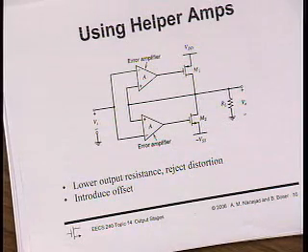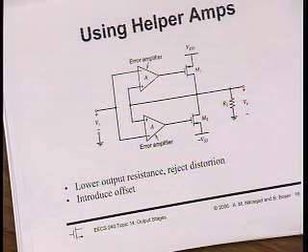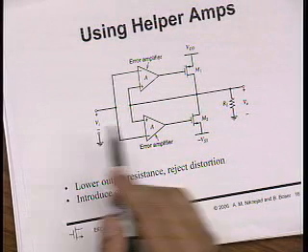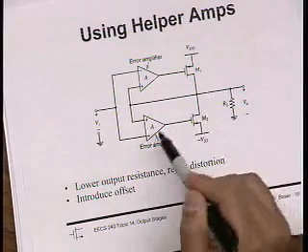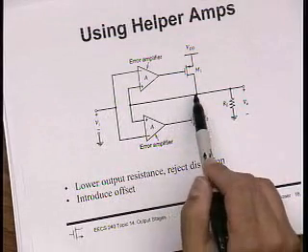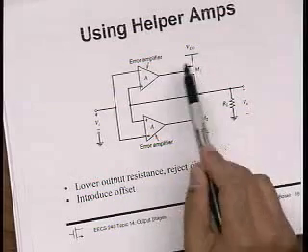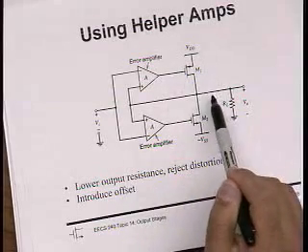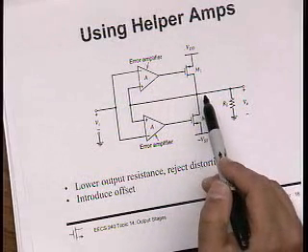So you have an amplifier of gain A, you have a transistor with output resistance RO. Yeah, RO over A, right? It lowers your output impedance by, in fact, A. As we said, it rejects the distortion, right? Because now my input-output characteristic is extremely linear. How does it do that? Well, this amplifier, in some ways, predistorts these gates so that the overall transfer characteristic is perfectly linear. That's a really nice thing about it.